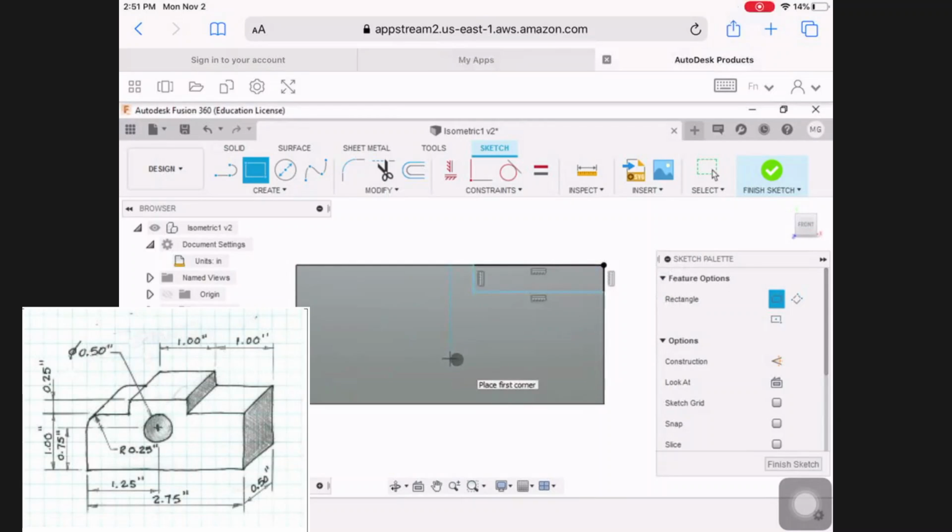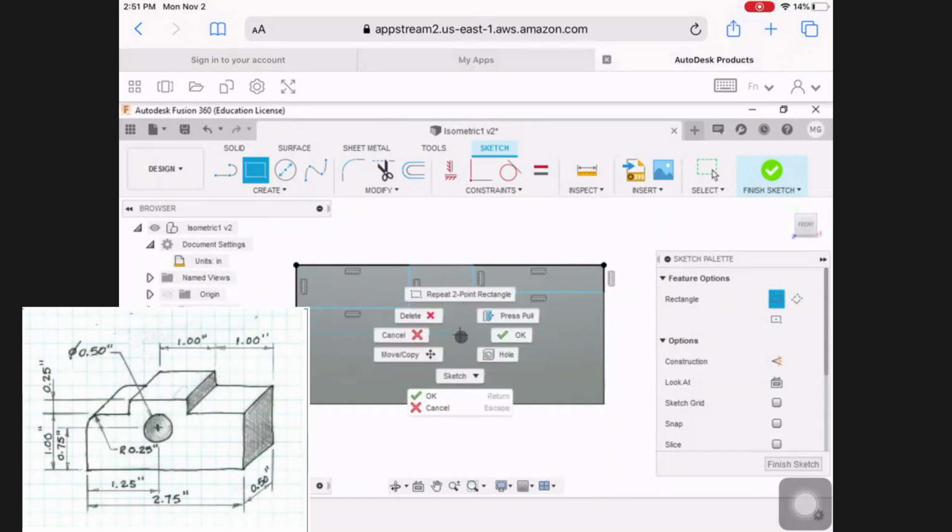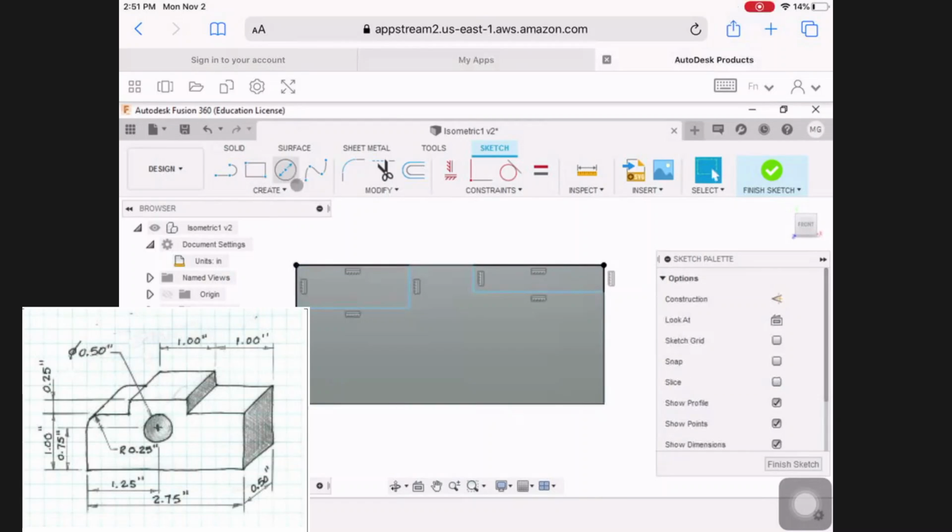And then there's also a rectangle that's taken out of this corner on the top left. I'll use the fillet command to round this after I cut using extrude. So I'm going to make another rectangle here and bring it in. Okay, so now right click OK to get out of the rectangle command.